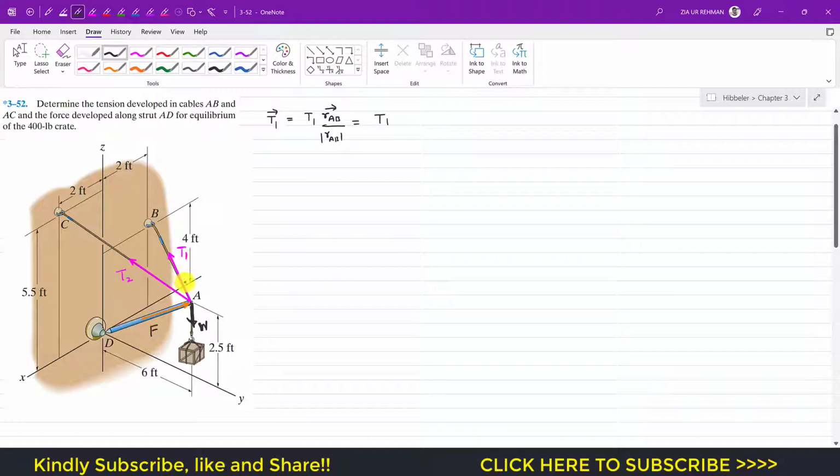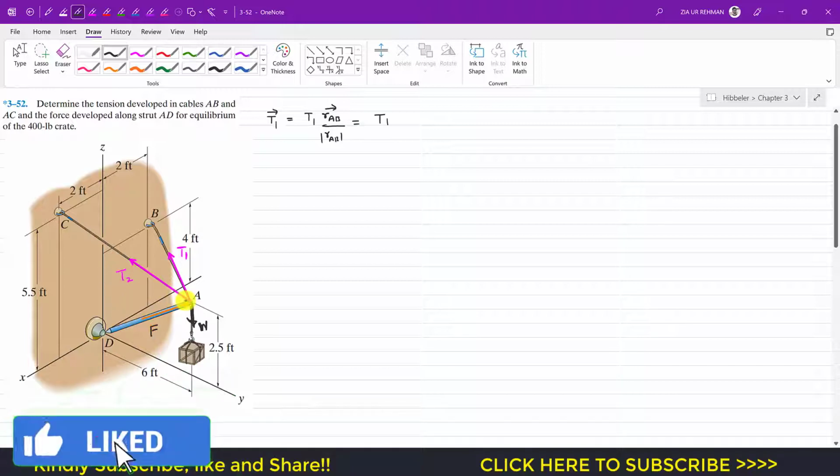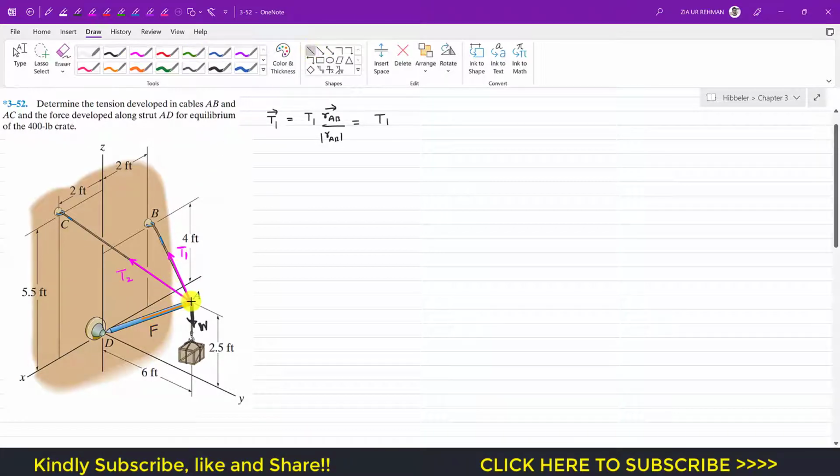To find the position vector from A to B, we need to move along the X, Y and Z axes to reach that point B. And we need to find out the distances between points A and B along the X, Y and Z axes. So if I move from A parallel to the Y axis, we will travel this much distance along the Y axis, and that will be in the negative Y direction. From here to here, this distance is 6 feet. So we need to move 6 feet in the negative J direction, so I will write minus 6J.